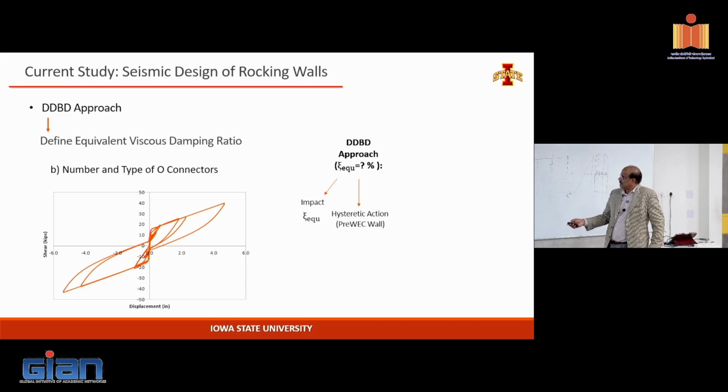What we found was that this curve comes within 30% or 25% of the peak displacement. The shakedown that takes place after the earthquake actually brings the structure back. So that is a guidance in terms of how much energy dissipation you want to put in. Some people think that more energy dissipation is good, and they put like 35% because connectors are cheap, I'll put more energy dissipation. But if you do that, you won't get the recentering.